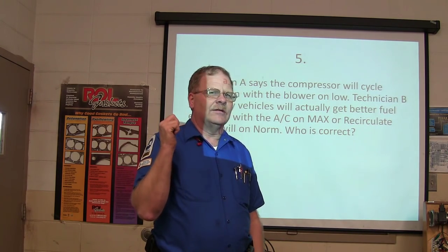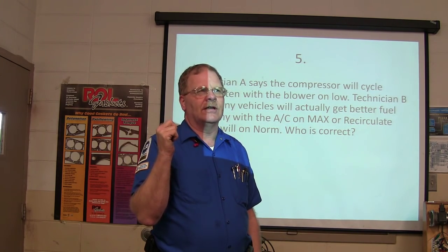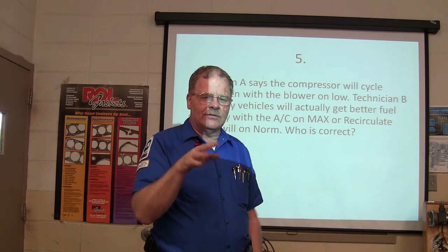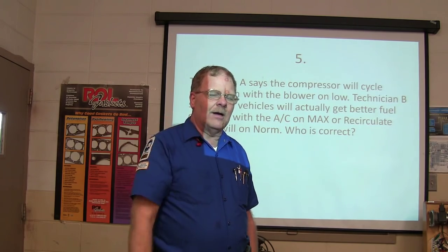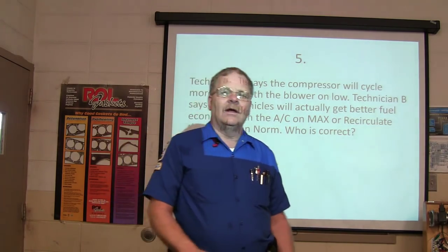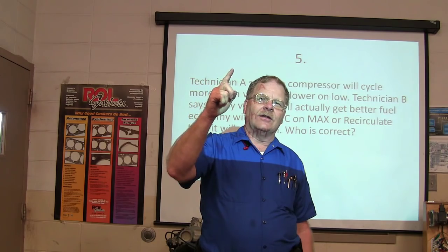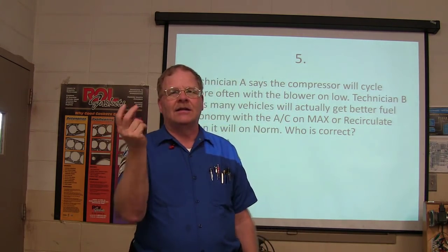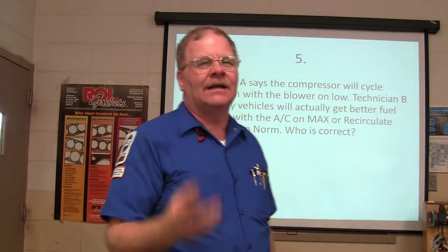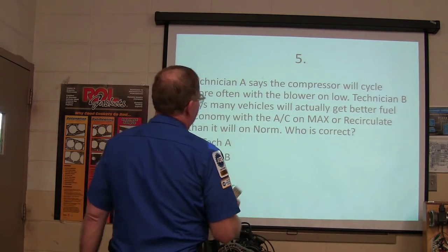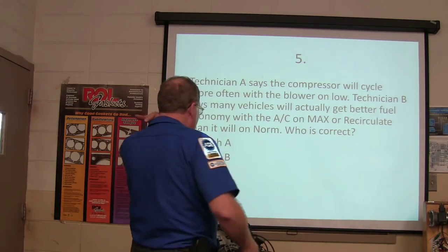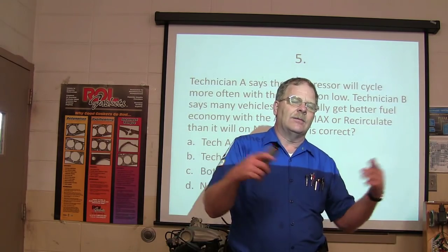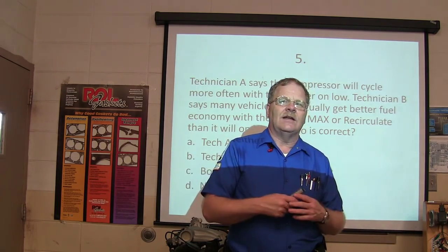Now we did that on one. This girl that was in here, a dual enrollment student, had a Dodge pickup, and hers was giving trouble. She'd drive it and the AC would quit. We put a thermometer in there and turned it on low blow, and it got down to 30, 28, 29, 26. It just kept getting colder and colder because she had a low pressure cutout switch that wasn't cutting out. I mean, it was always closed. And that's all it took to fix hers, a low pressure cutout switch. But you have to look at a wiring schematic to find out how the thing is wired up so you'll know what to do. You know what I mean? If you just go in there guessing.